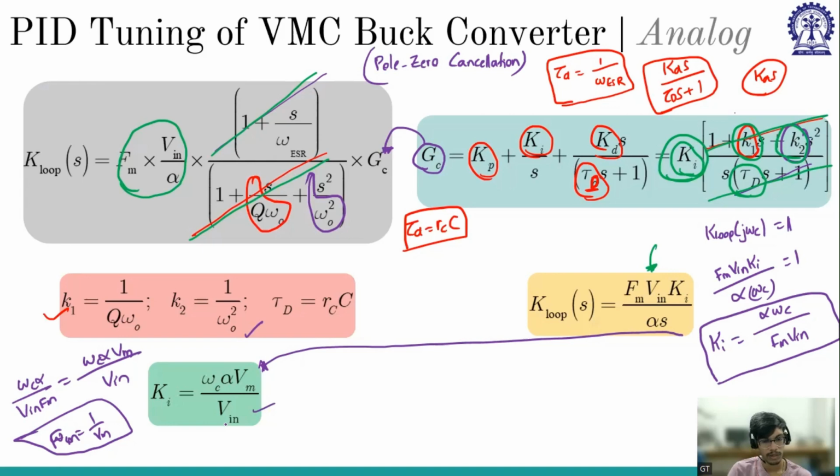Sir, the thing I observed in our organization is that they calculate all these, but at the end they still continue to tune. Yes. One issue with pole zero cancellation is that perfect pole zero cancellation can never be possible, because we are relying on ESR, LC values. Whatever values we consider may deviate in the hardware. So pole zero cancellation will not work exactly. The pole and zero will be quite close to each other, but they can never be cancelled with each other.